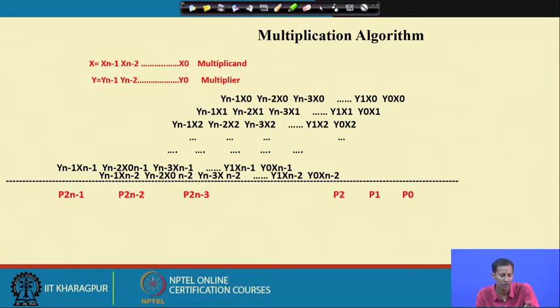So initially there were 4 bits for x, now I am shifting it by an additional 3 bits, left shift. So now the length becomes what? 7. And where will the other bit come from? As I am doing this bitwise addition operation to find the final products, at the final stage there will be the carry out.